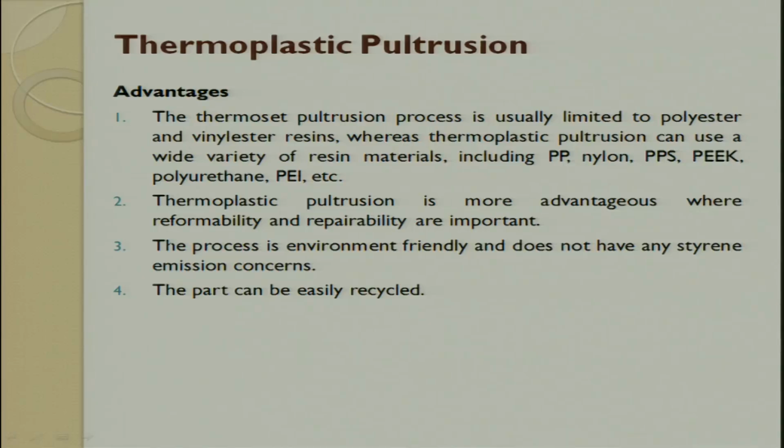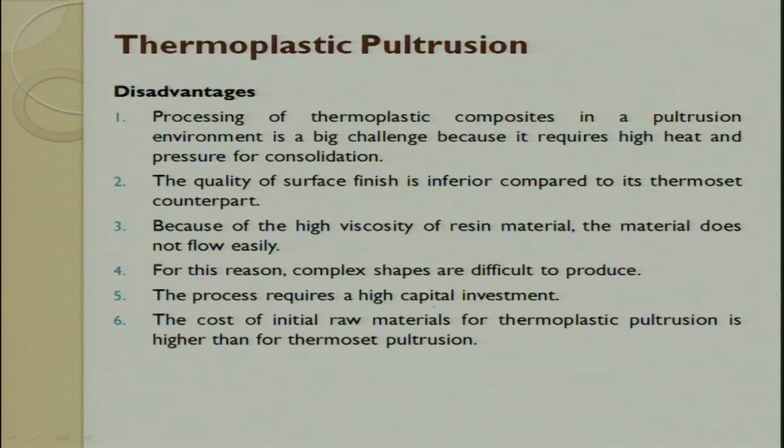So, what are the advantages? Reformability and repairability are possible as far as thermoplastic pultrusion is concerned, and the parts can be recycled. What are the disadvantages? The big challenge is that it requires high heating and pressure consolidation, which puts a lot of restrictions.